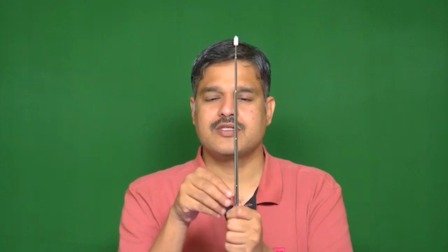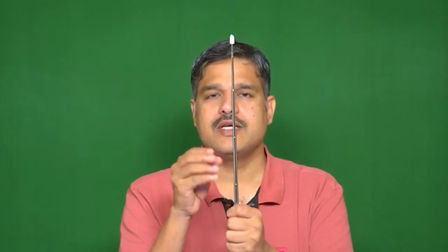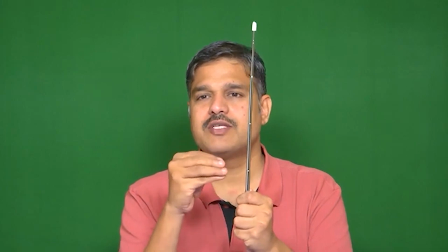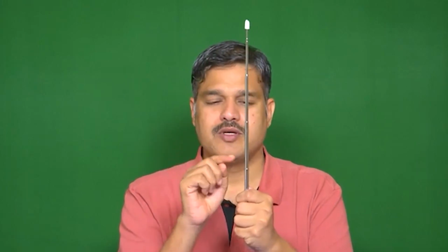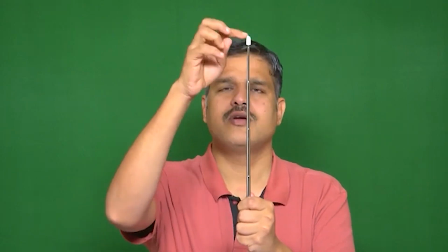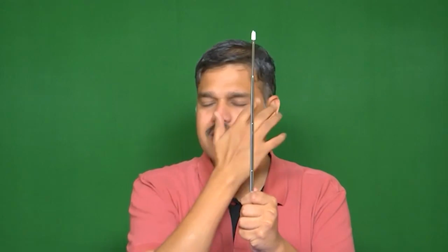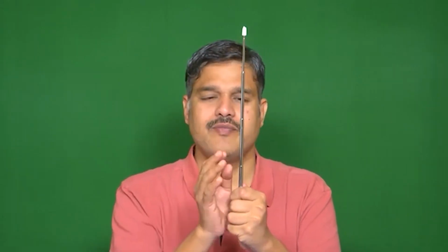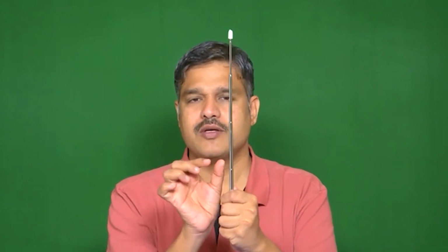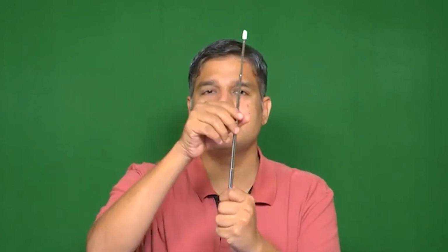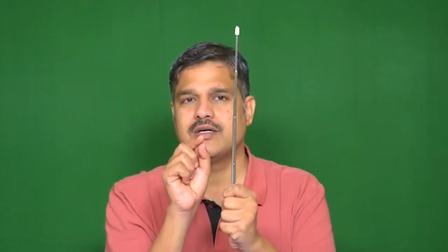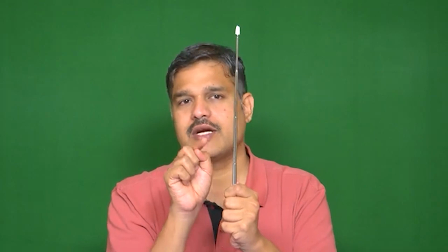If we take the structure like this, when we say displacement, which location and at which point of time? Suppose this is floor 1, floor 2, floor 3 and floor 4. In a lumped mass system, we are saying that at this location and also at this point. That is the reason our displacement function has two items in it: one is location and the second one is time.